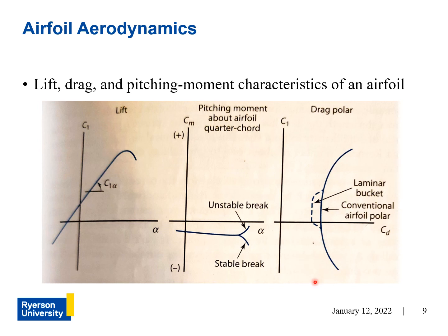So on this graph, the drag is on the horizontal axis, and the lift is represented by the vertical axis, which is usually in a 1-to-1 scale with the vertical axis of the lift curve plot. And the reason for that is because typically these two curves are side by side when you look at plots in literature.